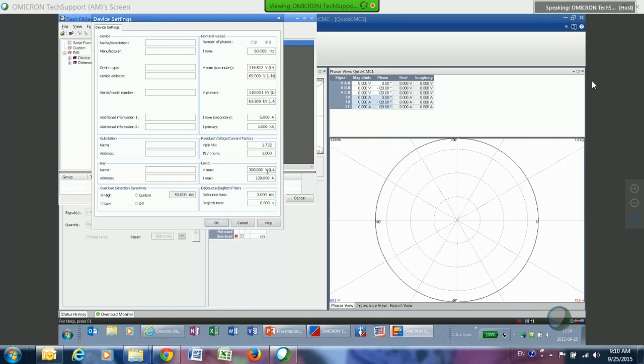But as we all know, sometimes the relays are not going to be able to handle a large amount of current for a long period of time, so you may want to limit how much current that test set puts out by selecting your iMax there. Your Vmax is basically the maximum voltage. The highest level that you can get is 600 volts phase to phase, but typically you can get 300 volts for 3-phase constant out there.